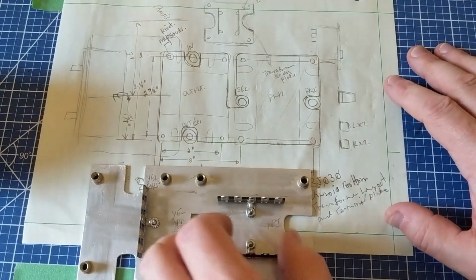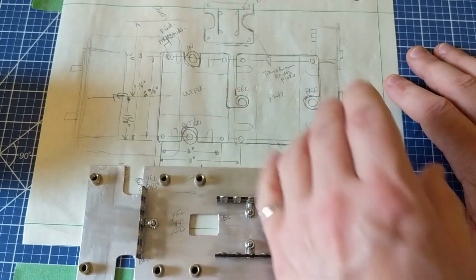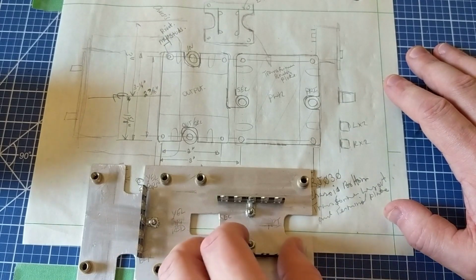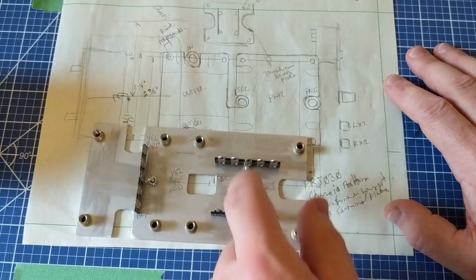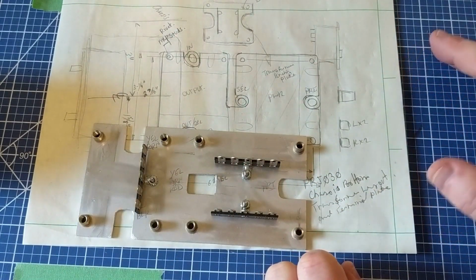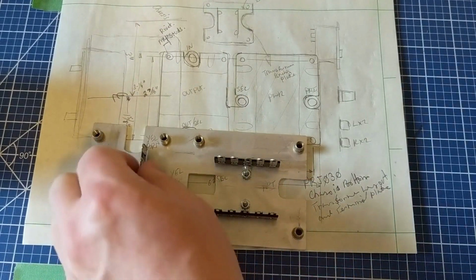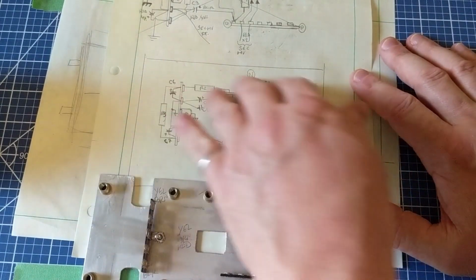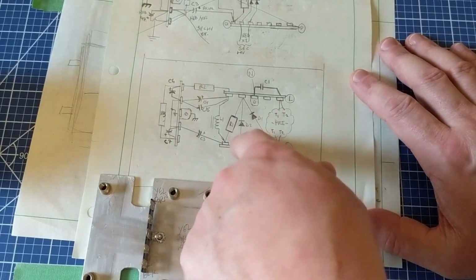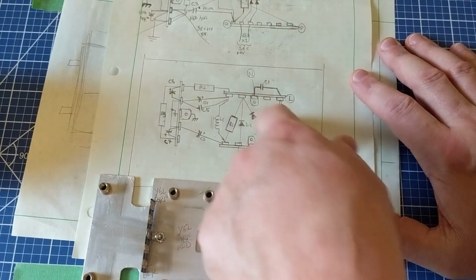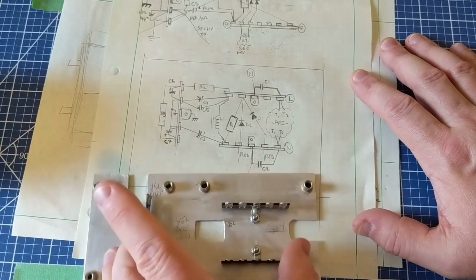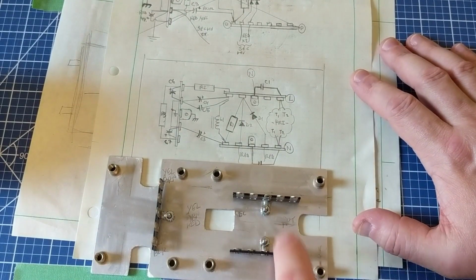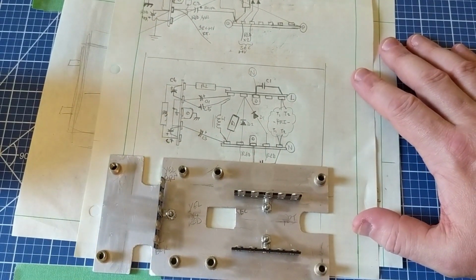To do this, I made some measurements and I drew a sketch up of where things should be, where all the holes are for the wires coming down out of the transformers. And then I determined tie points, tie strip points that I could use to create the high voltage circuit. From this, I created another point-to-point sketch showing me where all the resistor, diode, and capacitor and choke tie points would be that I would take advantage of in the circuit here. So there's no surprises. I know where everything goes. I know what all the tie points are being used for, and it's harder to make mistakes that way.